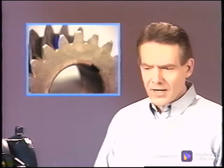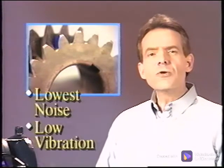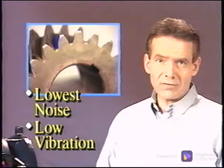Small errors in the center-to-center distance of the gears do not violate the meshing action. Another benefit is that the common tangent and the force always act in the same place and the same direction, producing the lowest noise and vibration levels.